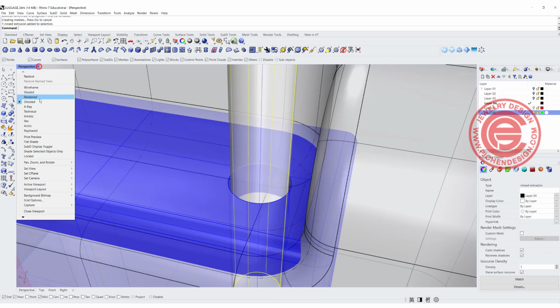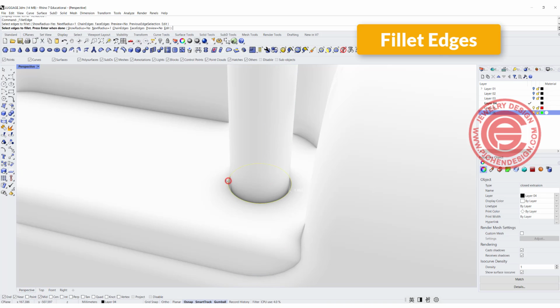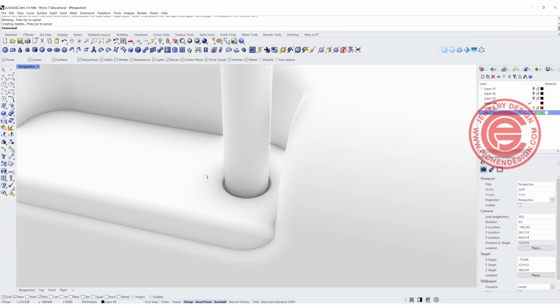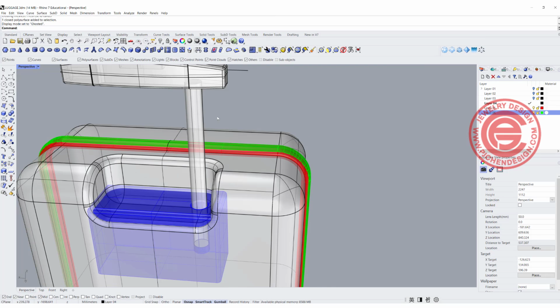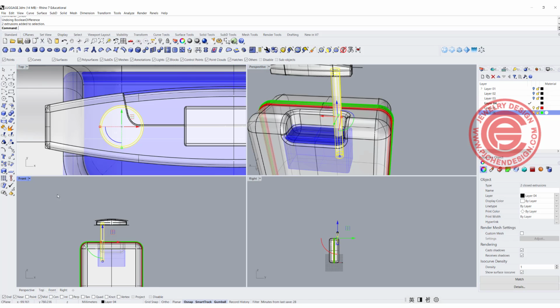And if you look at the render, it looks like it is a hole, but I would like to make it look nicer. So we want to do a fillet. It doesn't have to be something big, but as long as you've got something that looks like that, it is real. And two of them should be exactly the same. So I'm actually going to mirror that. So go back a step. I forgot to mirror that.